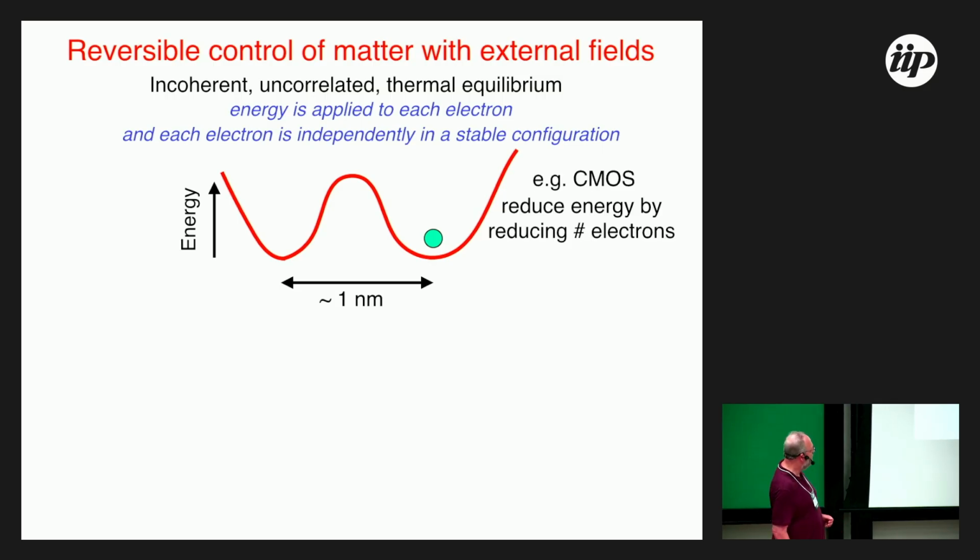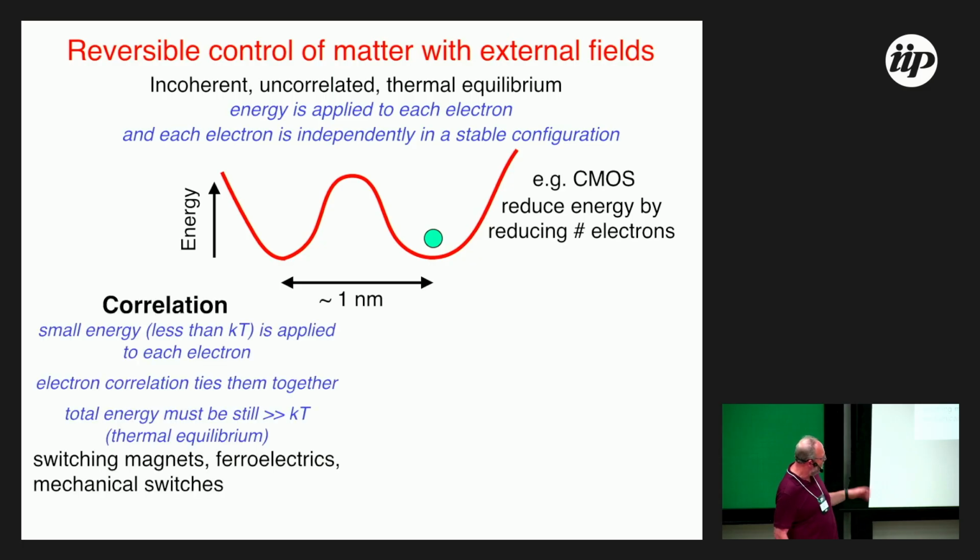And so then when you're looking to make faster and faster semiconductor electronic devices, VLSI, then you can try to reduce the energy by reducing the number of electrons that's switched. You reach a certain limit when you get to a very small number of electrons, because you could miscount, and then you get fluctuations in your voltage on your downstream gates, which is bad. And so you get some kind of fundamental limit related to the individual electron and then the number of them.